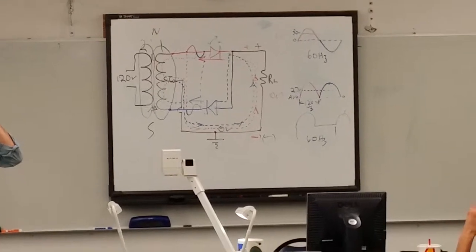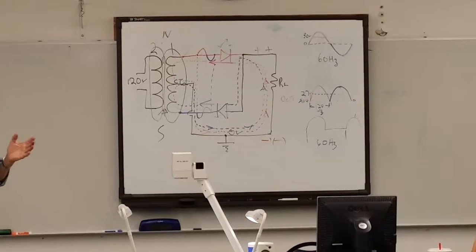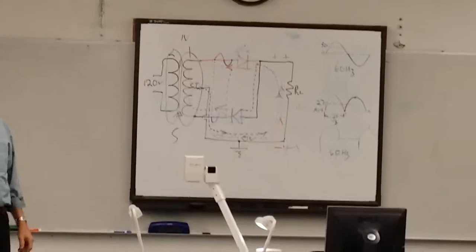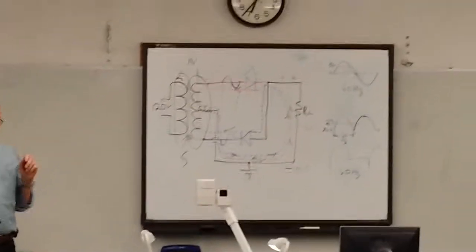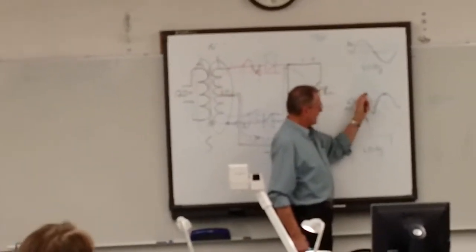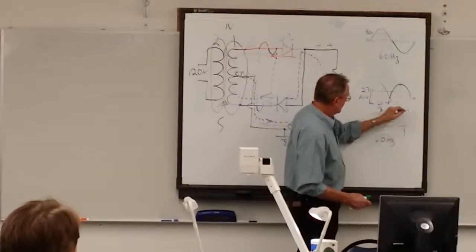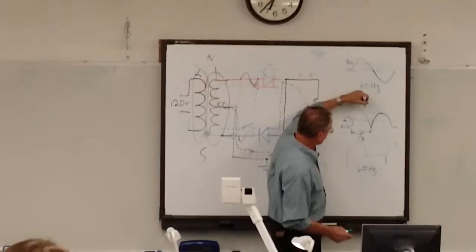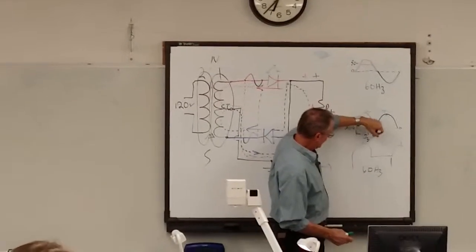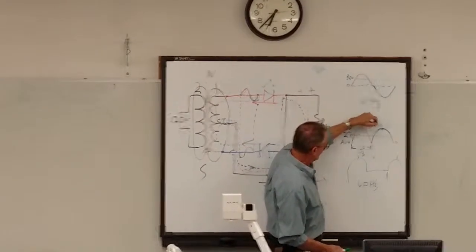Questions? That's a full-wave conventional, not used a whole lot, because you don't gain anything, other than if you're gonna filter. If this required a 1,000 microfarad capacitor here to here, this distance from that peak to that peak is half. You can see from here to there, that's half. It's 1/2 of that, you see that? If this is X, this is X over 2.